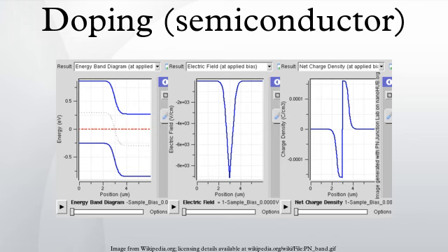This effect is shown in a band diagram. The band diagram typically indicates the variation in the valence band and conduction band edges versus some spatial dimension, often denoted x. The Fermi level is also usually indicated in the diagram. Sometimes the intrinsic Fermi level, Ei, which is the Fermi level in the absence of doping, is shown. These diagrams are useful in explaining the operation of many kinds of semiconductor devices.